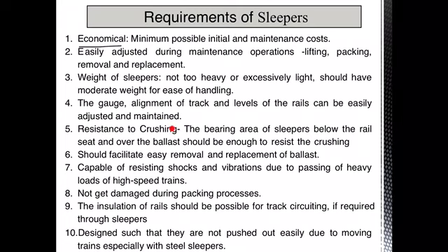And it should have resistance to crushing. The bearing area of the sleepers below the rail seat and over the ballast should be enough to resist the crushing of the sleeper due to the rail seat and the crushing of the ballast underneath the sleepers. Coming to the design aspect, the sleeper design and spacing should be such that it facilitates easy removal and replacement of the ballast below.